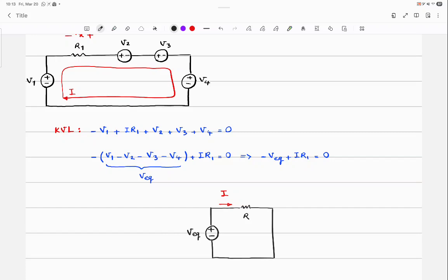They would provide 0 because one of them is trying to give positive 1.5 and the other one is canceling. But when you put them head to back, then it will create 3 volts for you, right? So can you tell me which voltage sources in this setup are enforcing V1?